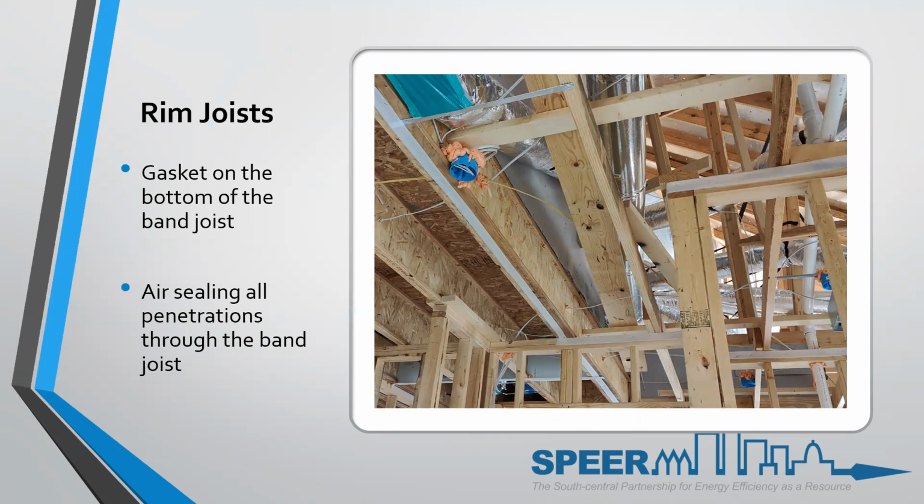Even when the band joist is over conditioned space, air sealing must also be done. So here we see a gasket that was installed below that band joist. This is actually over the garage, but there's a gasket underneath that band joist. Actually, this is not. This is over conditioned space, and that's the second floor. And in this instance, they felt it was necessary to put the gasket, which in our world is, because that's not a perfectly level bottom of that beam or TJI where the sheetrock's going to meet. And every gap that you don't have a nail or screw for the sheetrock is leaving a pathway for air to go through. So installing the gasket here is a great way to do that.